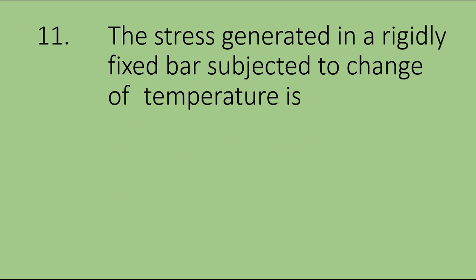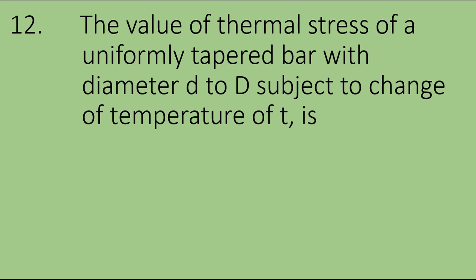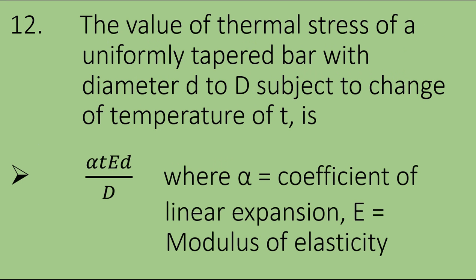11. The stress generated in a rigidly fixed bar subjected to change of temperature is. Answer: thermal stress. 12. The value of thermal stress of a uniformly tapered bar with diameter small d to capital D subject to change of temperature of T, is. Answer: alpha T E small d by capital D, where alpha equals coefficient of linear expansion, E equals modulus of elasticity.